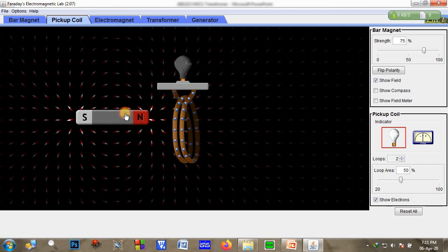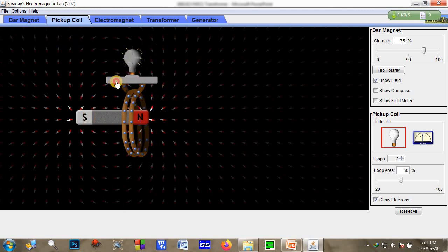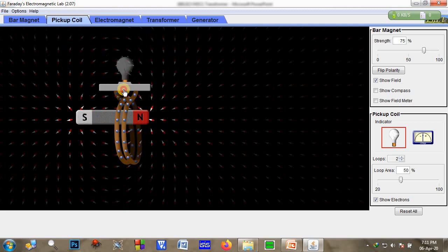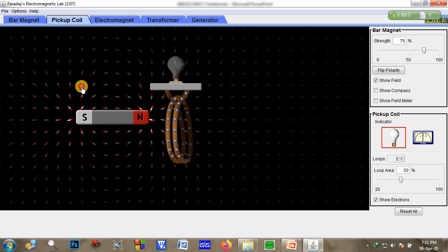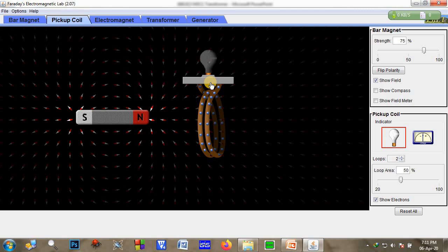The second type we have discussed, so now I am going to keep this magnet constant and I am going to vary this conductor. So you can see if I vary this conductor, then also an EMF is induced because there is a change of flux linking with this conductor. As I move it fast, the magnitude will be directly proportional. So the EMF induced in this way, by moving the coil and fixing the magnetic flux, we call dynamically induced EMF.